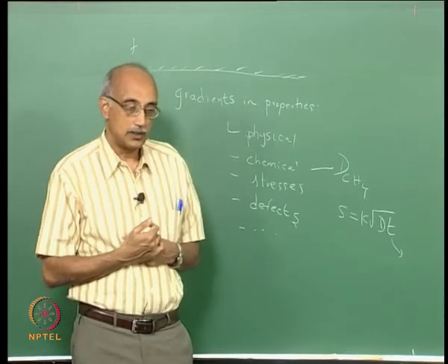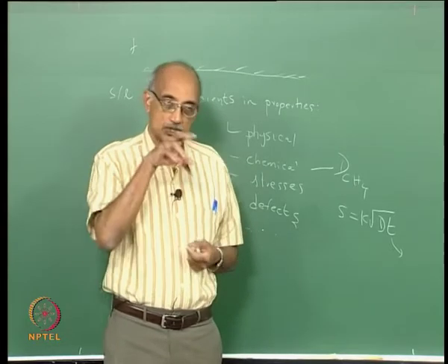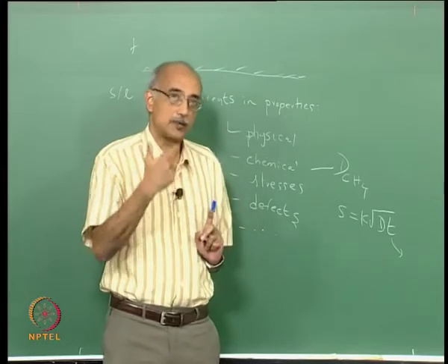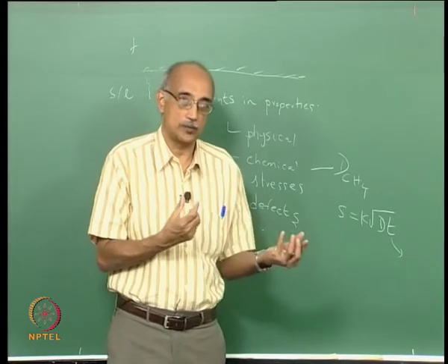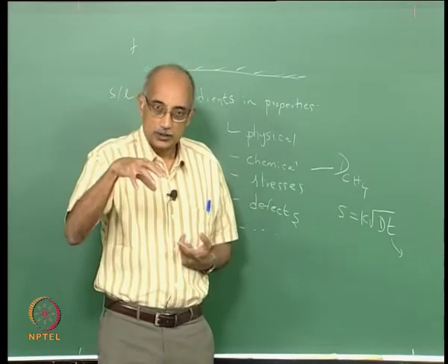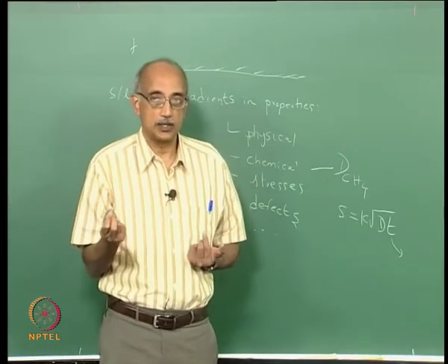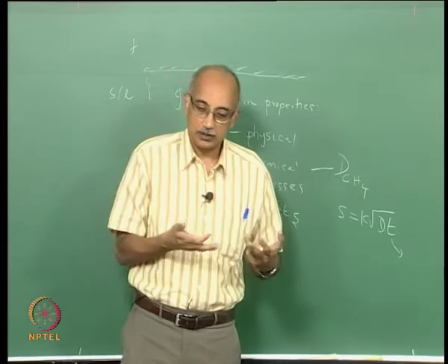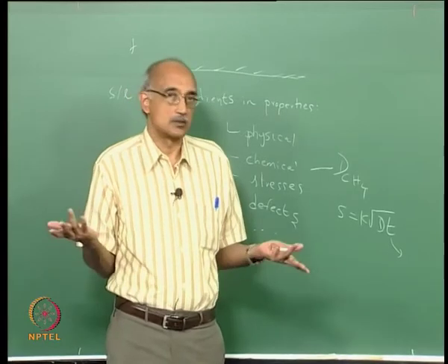But if you now let the penetration continue, let us say that you have a very porous aluminum particle and this oxygen can diffuse into the interior of the particle, then the composition of the entire particle will slowly change, and the particle itself will eventually be converted from an aluminum particle to an aluminum oxide particle through the surface and the subsurface regions. Now, will the core of the particle also be converted? That is very unlikely to happen. In other words, you cannot convert aluminum metal to ceramic alumina simply by exposing it to oxygen. That is basically what it means.